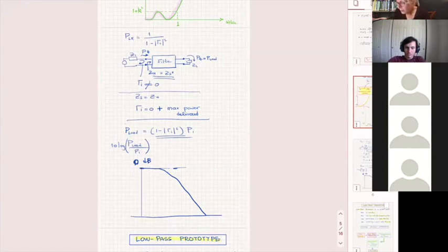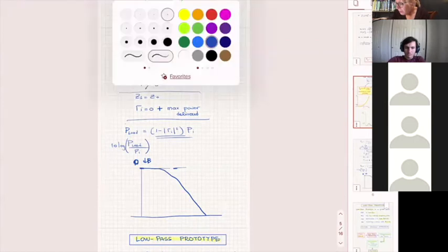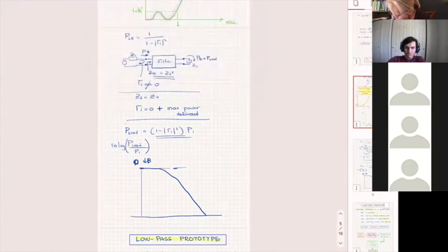But if I were to use a Chebyshev design, then it would look like this. See, what I gain from Chebyshev is what I see here, which I call rejection. Why do I call rejection? Because ideally in a low pass filter, you remember how we showed the low pass filters before with simplicity? We want the low frequencies to go in, and we would like to be really clean as we cut the high frequencies.